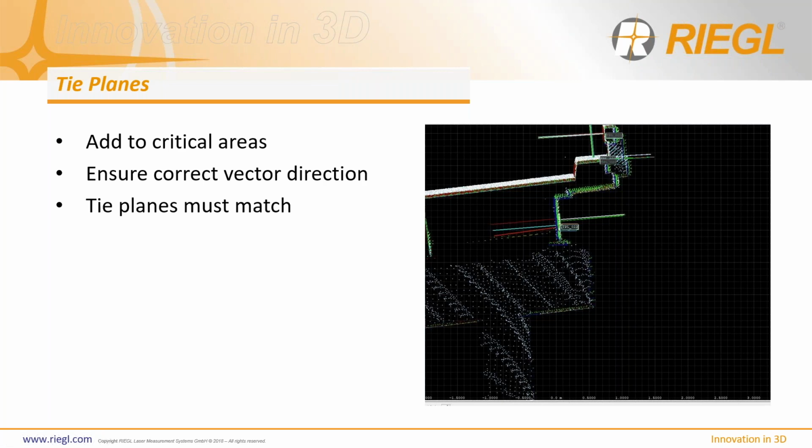All right, if you came up with because one of them saw it on the way through the bridge, the other saw it on the way out of the bridge, and it's an I-beam, so it's wider than that, you're right. So this is a bad plane to pick. You've got to be very careful that you're not trying to shove two surfaces together that don't belong. So if you're going to do this, take your time, make sure that things match correctly. By calling them tie planes, they really must match. They can't just sort of match. They really need to be the correct surface that you're matching them to.